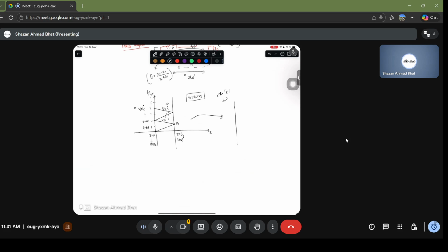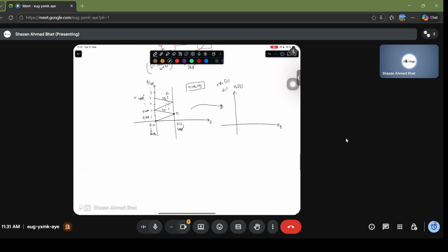Then from this lattice diagram, you draw the variation of load voltage with respect to time, and you draw a time scale on it. So this is basically a transient variation of the load voltage. So you have 0, you have time TD, 2 TD, 3 TD, and you know that there will be no voltage in this time because it takes time TD to reach the load. So the voltage will start from TD, it will go on increasing, and then it will reach some maximum value.